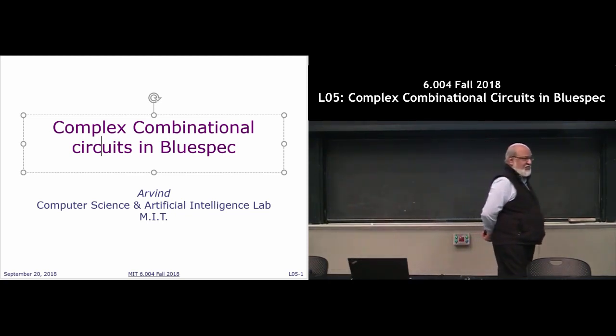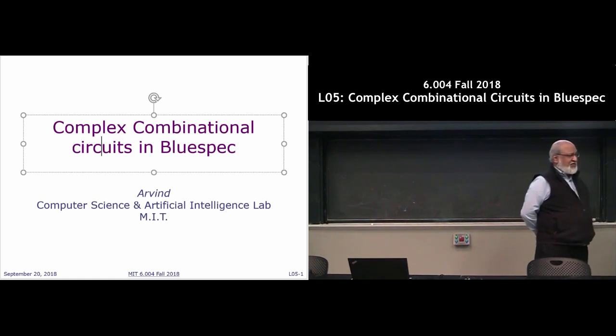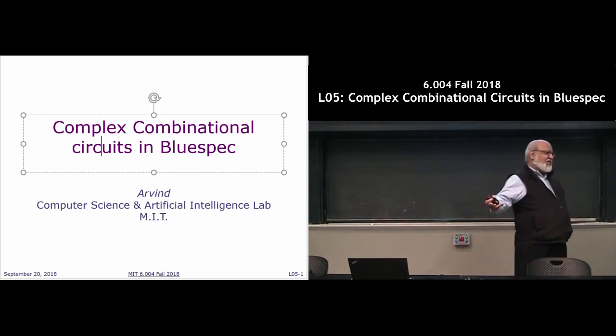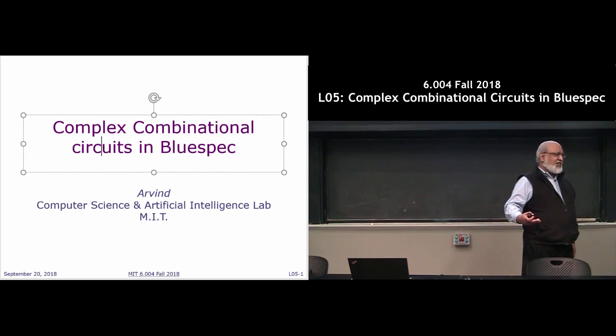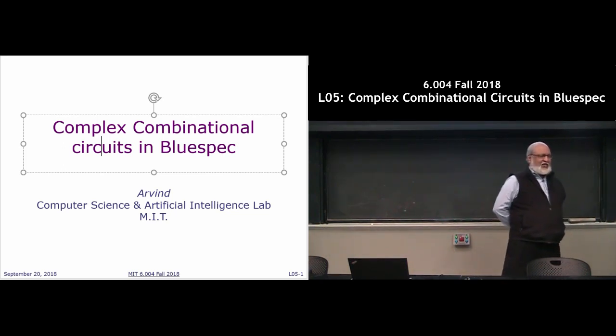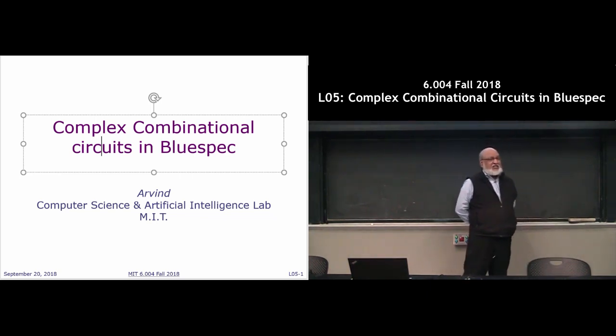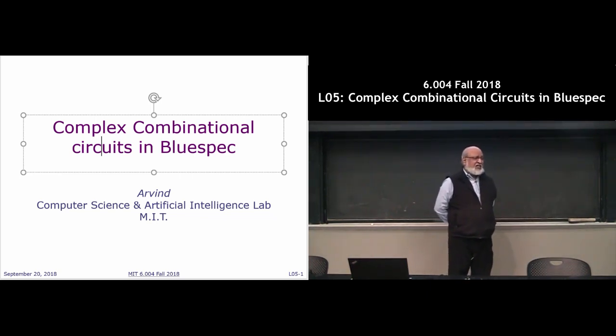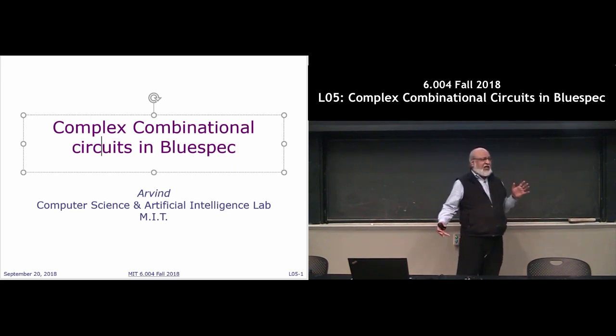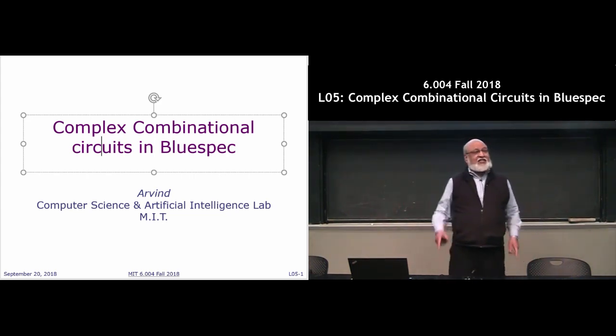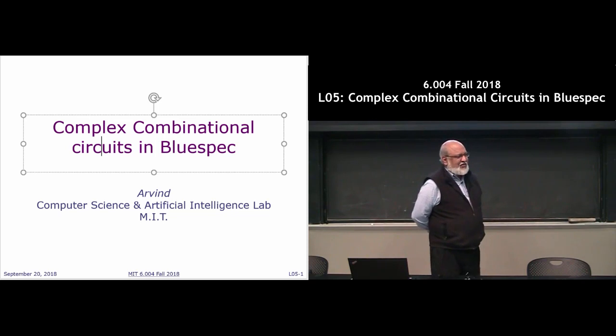It's really a vector. It's always fixed size. So you have declared the type to be 16 in this, and you can select from it, and you'll be able to assign to it. But you can't think of it in terms of software vector. It's just a naming convenience. So vector is, you had lots of things to name, and instead of giving them 16 different names, we'll call it x, and then I can refer to x0, x1, x2. Whenever I refer to x1, x0, I mean that int 8. So it's only a naming device.